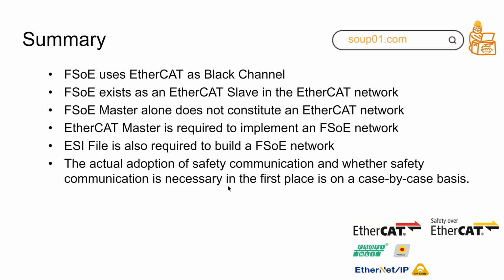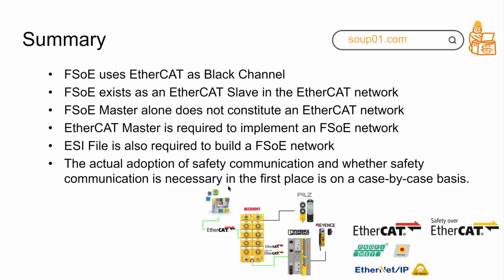And deciding which type of safety communication to use, and even whether to use safety communication or not, is case by case. Okay, so here is just a comparison. Here is an FSoE master, Beckhoff. And if you don't have TwinCAT, or this EtherCAT master, this one will not work. It means that you need an EtherCAT master to generate the EtherCAT frame.